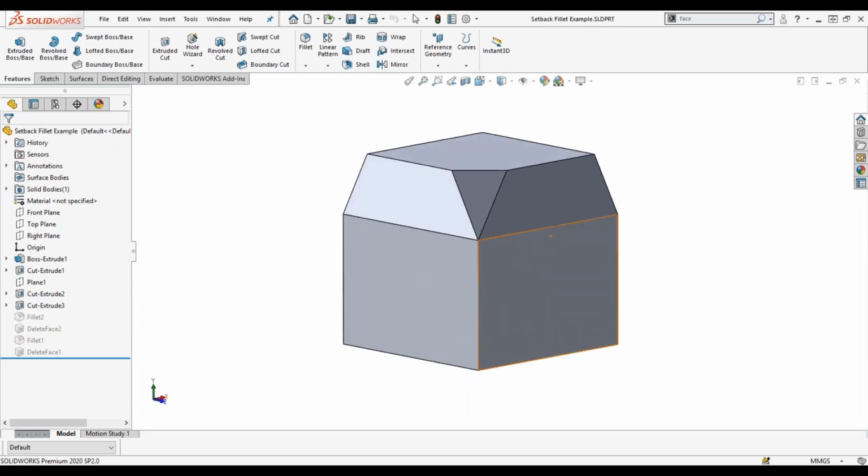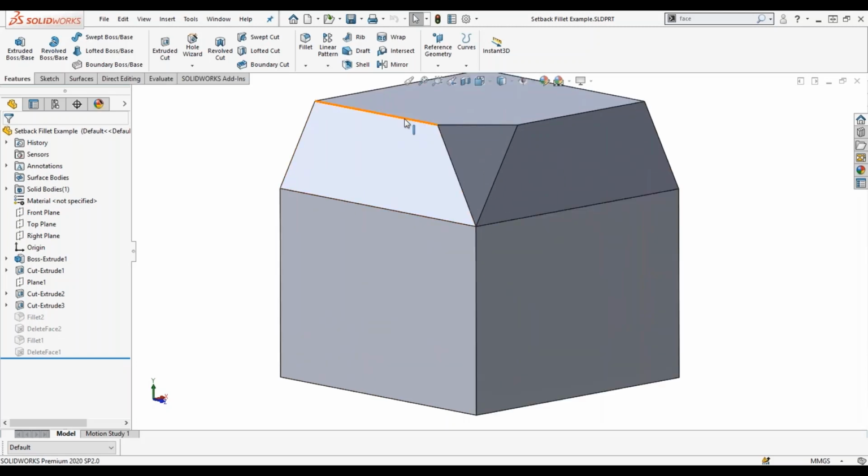This is also going to combine two options in one. So we have this intersection in this part right here, and we want to add all of our fillets to it. We have specific radii that we want to add to each of these edges. Down at the bottom, we want this edge and this edge to be 10 millimeter radius. We want this edge and this edge to also be 10, but we want these sides to be 5 millimeters and this one in the middle to be a little bit larger and have a 15 millimeter radius.